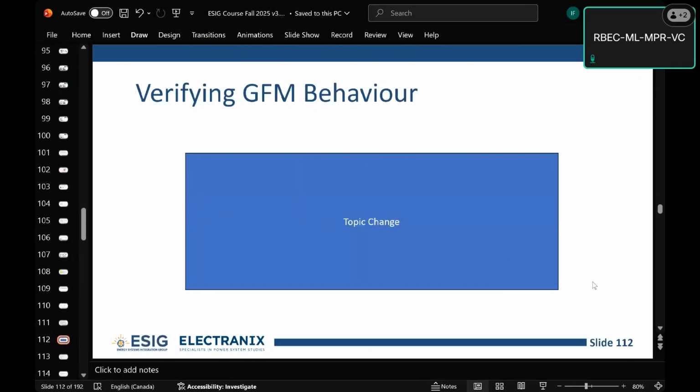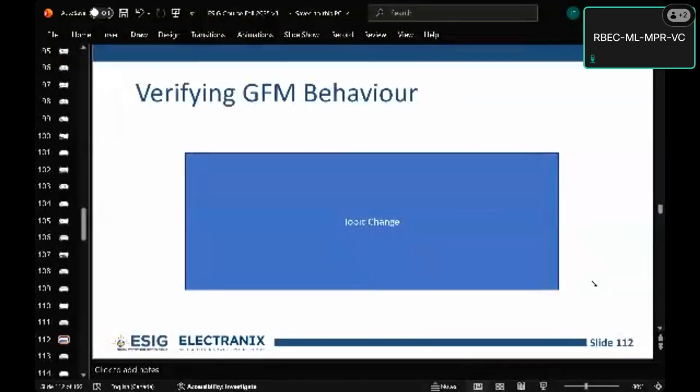But yeah, the huge consideration too is the more grid forming you get in a small area or a weak grid, or a lot of grid forming in a strong system, is there are really aggressive controllers. Or sorry, they're just aggressive. They can interact with each other, right? Is what I'm saying. So the same way as a synchronous machine, if you put a bunch of synchronous machines in an area, do you expect them to aggressively fight with each other? No, well, they could. Well, it gets into the software base. There's a lot more errors you can make when tuning an IBR, right? And those errors are magnified in a many GFM.